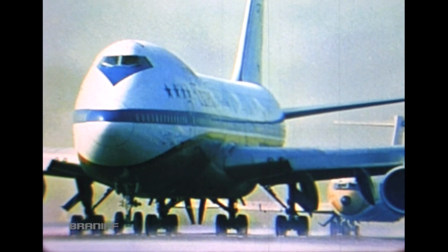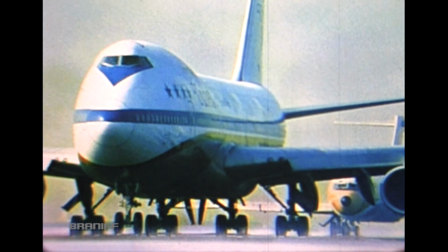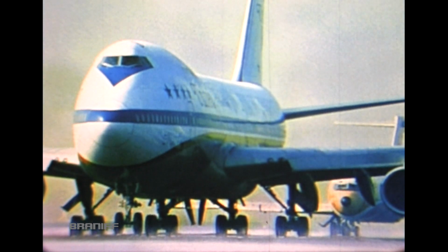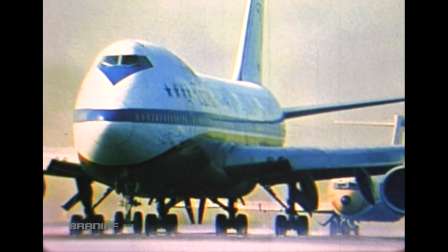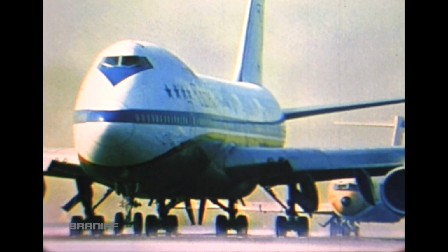The use of reverse thrust at any time may cause snow or slush to be blown onto the airplane or into the engines. Airplane surfaces must be re-inspected after using reverse thrust. Maintain a greater distance than normal between airplanes when taxiing on ice, slush, or snow-covered areas. Snow or water blown up by another airplane's exhaust may freeze on contact with your airplane. This may be difficult to detect.